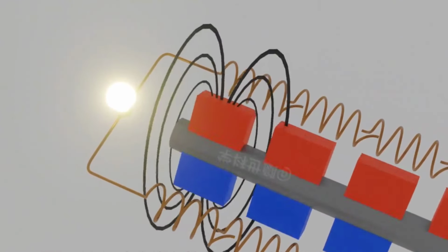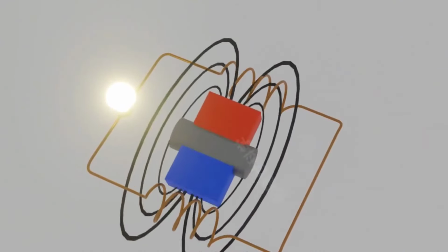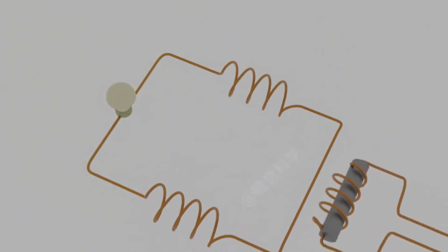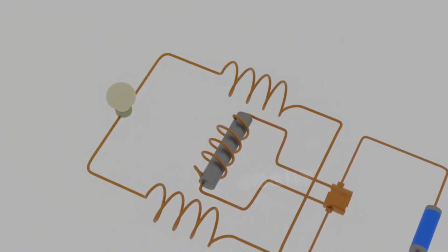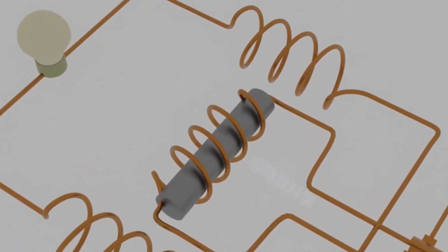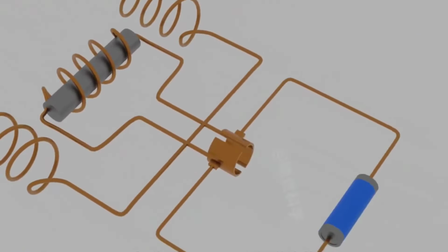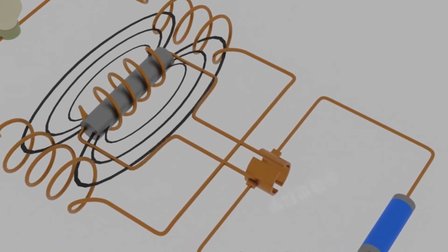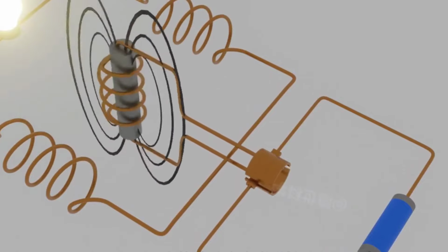We can increase the magnetic field without increasing the size. This can be achieved by replacing the magnets on the rotor with coils, because the magnetic field can not only be obtained from permanent magnets, but also be created with copper coils. The coils with power will produce magnetism. This is widely used in large generators.